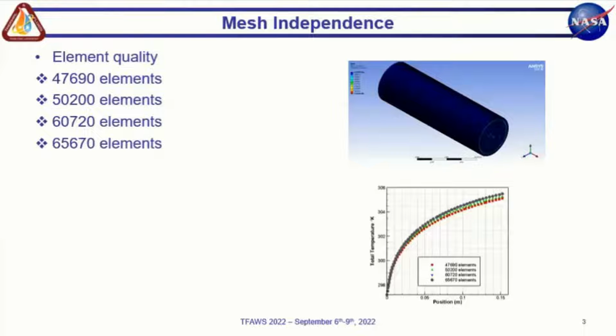Now I have to talk a little bit about the assumptions that went into the simulation of nanofluids heat transfer. Well, because physically you have two phases in a nanofluid, in this case you have the water, and then you have the aluminum oxide particles suspended in the water. And there are two approaches as to how you model this fluid.